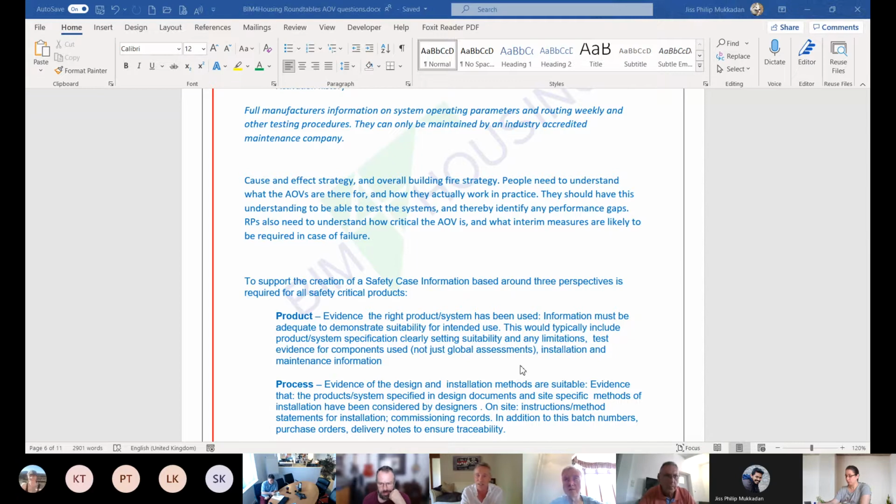So yes, it's important, going back to the activation history or the event log, to understand how many operations it's actually performed. Because if it's got a reliability class of 1,050, but it's actually being used for day-to-day ventilation to stop overheating, it's going to massively shorten the life, typically not of the hinges of the window or the vent or the louver, but potentially of the actuator. Therefore, a replacement is needed.